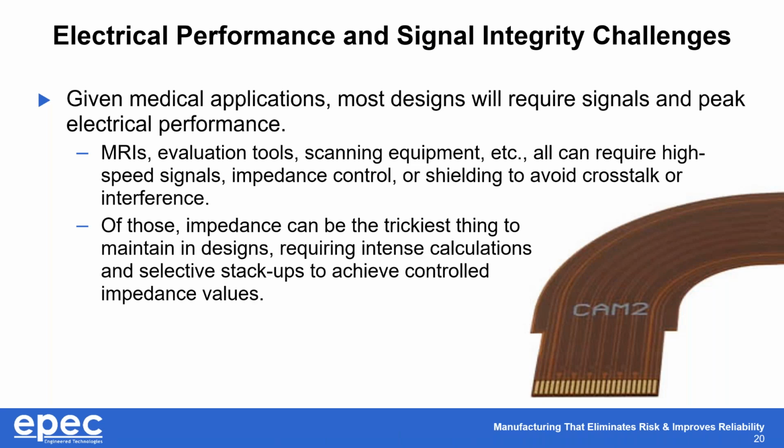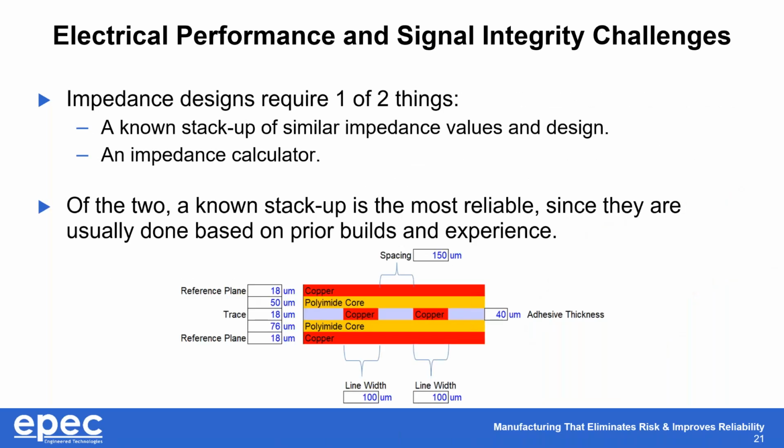And so you'll end up relying on either those intense calculations using a known calculation software, or using stack-ups perhaps that have been tried and tested to achieve controlled impedance values. And so, as I was saying, impedance designs are going to require one of those two things.